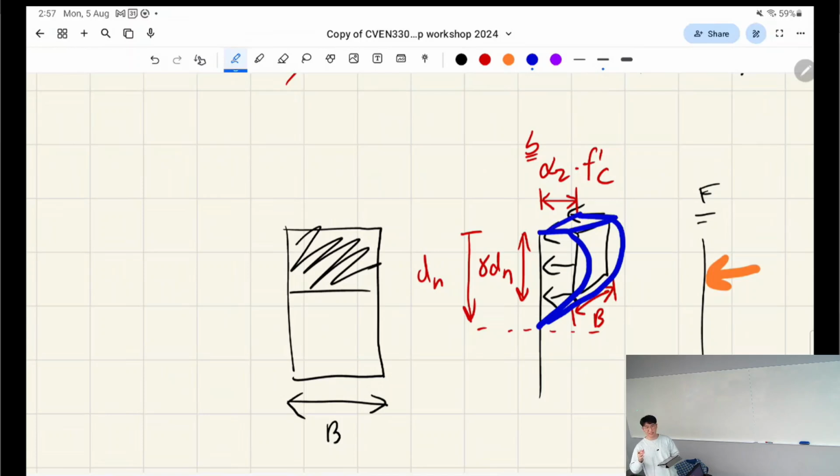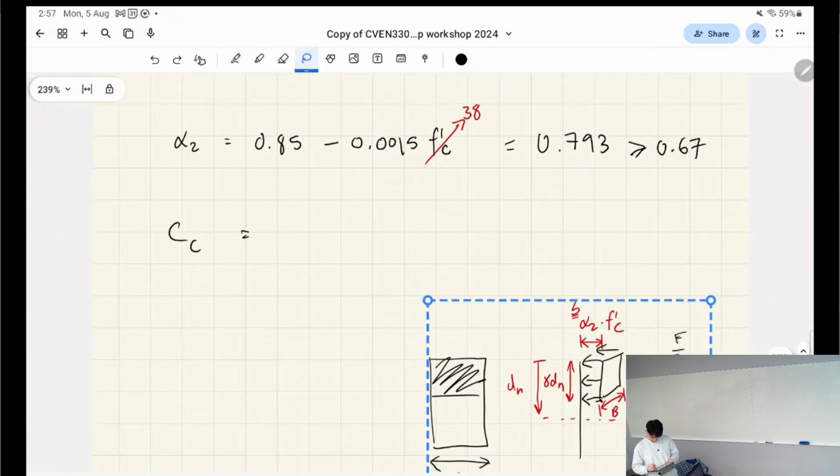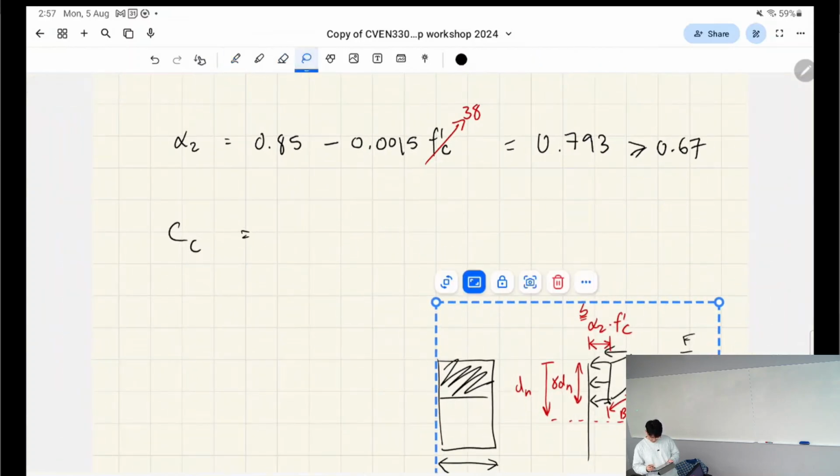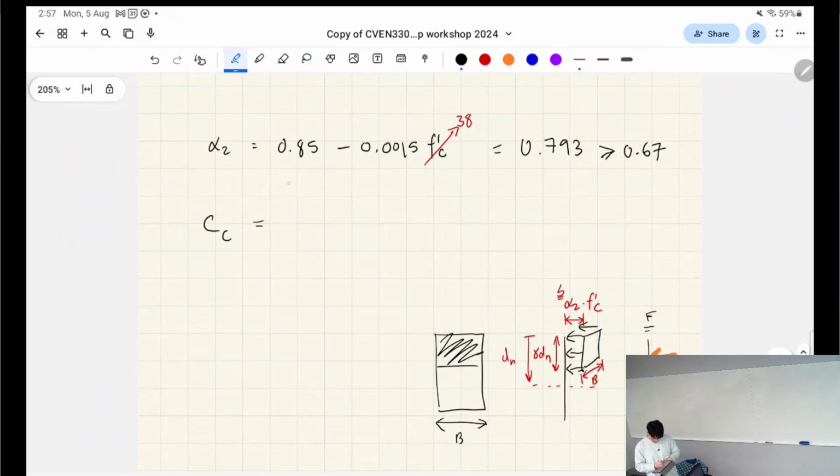We've basically pretended it's a rectangle, shifted it up, and reduced the maximum of the parabola's peak. So this is actually the easy version. This is not unique to the Australian standards, but Australians love the rectangular stress block, right?